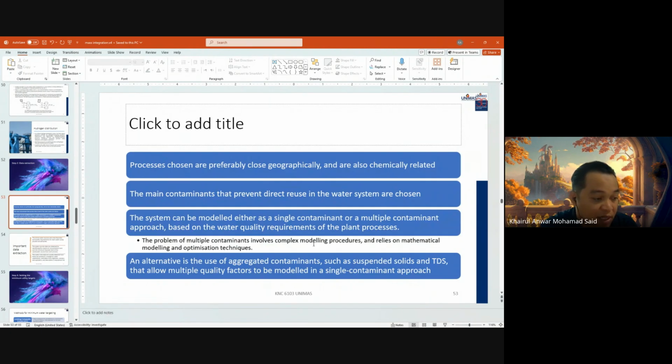Instead, we extract the limiting data for everything. We ask what is the absolute maximum concentration of contaminant this equipment can tolerate before it corrodes or fails. Next, for every source, we determine the maximum outlet concentration. This limiting data establishes our thermodynamic boundary.